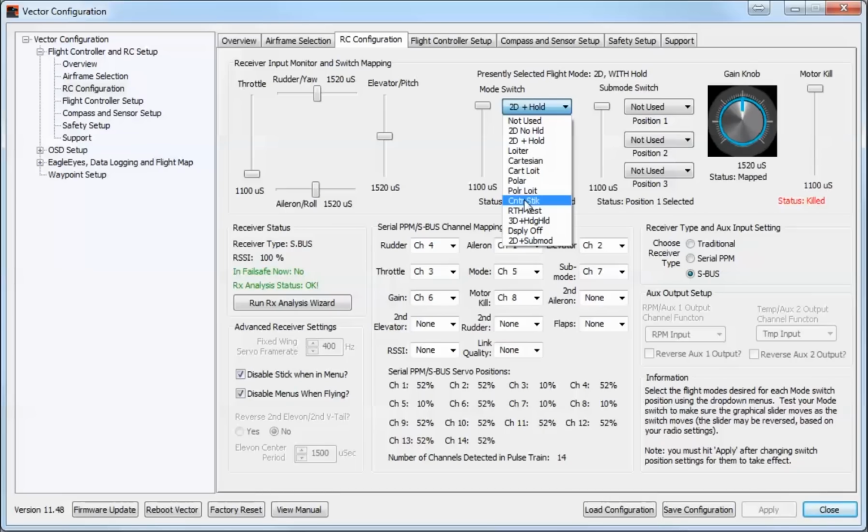The key is though, let's say for example you take off, you fly out 100 feet in front of you, you then go up to a good couple of hundred feet, make sure you're nice and high. If you then give a full aileron input, you will find that your multi-rotor will literally roll itself all the way around its own axis and basically flip right over. Once you've got to a point where you're happy it's not going to completely stall, then if you release the sticks, you'll find that it self-stabilizes itself. So it will pull itself out of the dive, but it needs enough altitude to do it.